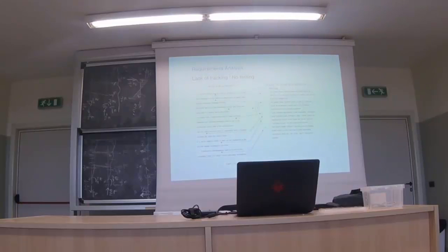This is natural language being converted to processing. The lander flight software should cyclically check the state of each of the 3 touchdown sensors, one per leg, at 100 Hz during landing. It should be able to cyclically check the touchdown event state with or without touchdown event generation enabled. Upon enabling touchdown event generation, the software should attempt to detect a failed sensor by marking the sensor bad when it indicates touchdown state on 2 consecutive reads.